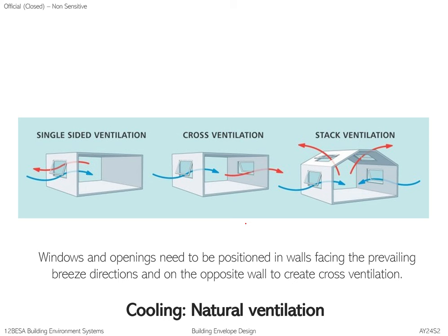Cross ventilation used to be one of the questions that your DS tutor will ask you: how do you factor in cross ventilation? I'm not sure whether it still is, but it is one of the basic things that you have to factor into the design of apartments. Very important, actually. For example, the position of your living room door, not so much, but the position of your toilet doors in relation to your bedroom doors, and how deep your bedrooms are. What is the spacing between them? These kinds of parameters you have to play around with and massage to achieve cross ventilation.